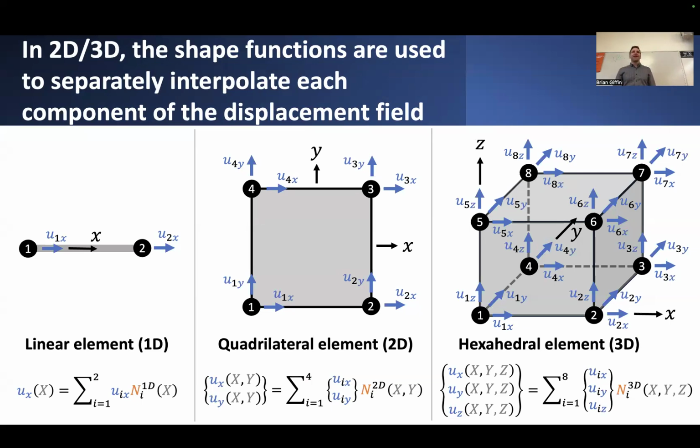But before we dive into some of the details, I'll point out that all of these expressions assume that these nodal shape functions are expressible in terms of spatial coordinates. They might vary as a function of position, x, y, and maybe z in 3 dimensions. But in general, we don't usually specify these shape functions in terms of these global coordinates, x, y, or z.